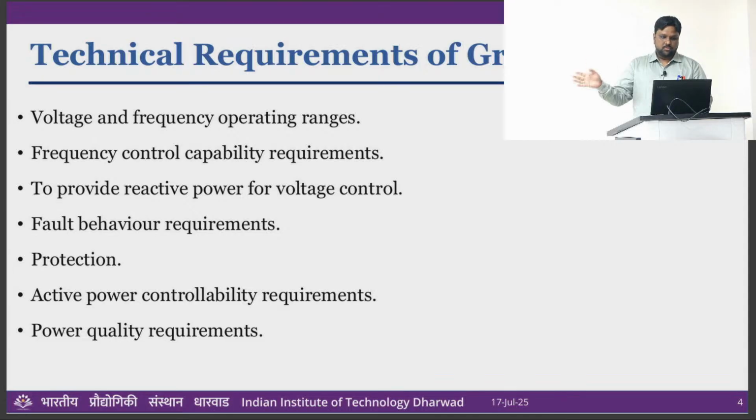Okay. So, these grid codes, what I am going to say, are more stringent or more strict at the transmission level. Okay. Distribution level, they can relax some of the grid codes. At the transmission level, when you talk about let us say megawatt scale power generation or load, and you want to connect at a transmission level voltage, kilovolt level, at those times even a small disturbance can create big hazards. Okay. Sometimes it results in a pure blackout. It has been already observed in different parts of the globe.